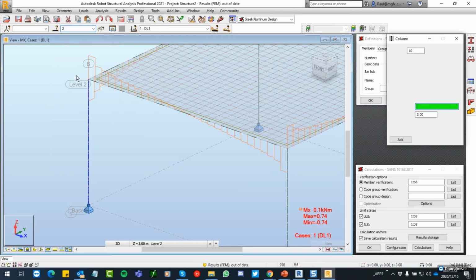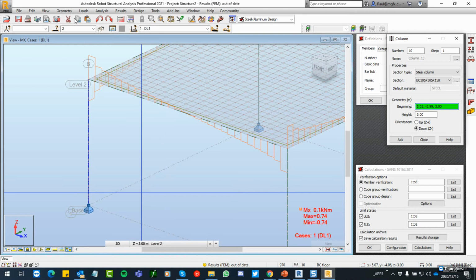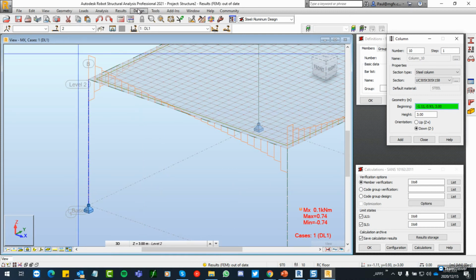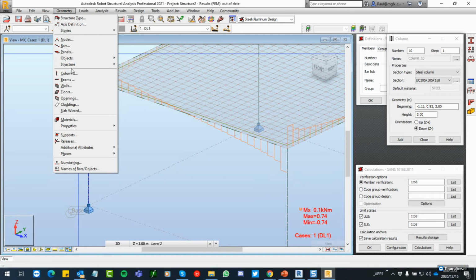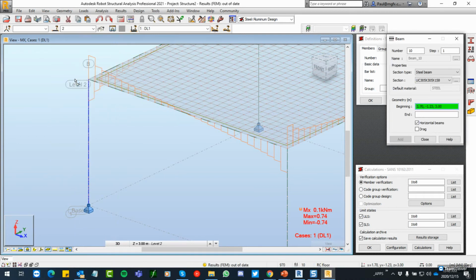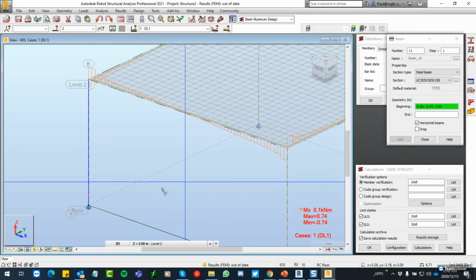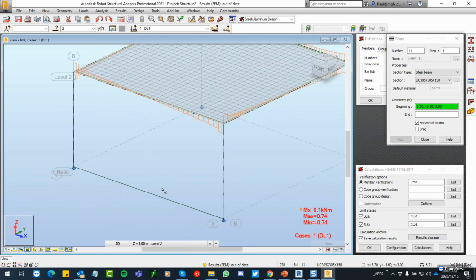There you'll be able to draw columns, and you'll be able to draw columns with beams maybe. So let's put this beam across on that work plane. Save. Let's just update the model as well. You see if the beam comes through. Here's the type of beam that it's putting in. You see that it picks it up from a database. It's a steel beam. It's using that UC type.